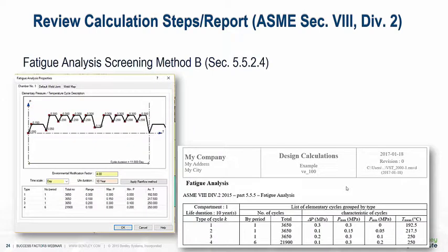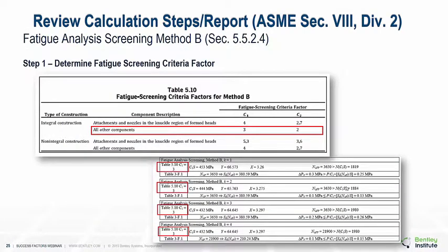The distinct fatigue cycles obtained by applying the Rainflow method to the load histogram are listed in the beginning of the report, as shown to the right as a table. This table is most important since it provides the most critical data for the fatigue analysis and would be frequently referred to in this presentation. In fatigue analysis, each individual weld is analyzed separately for fatigue. In our example, we will consider only the weld tag W1.